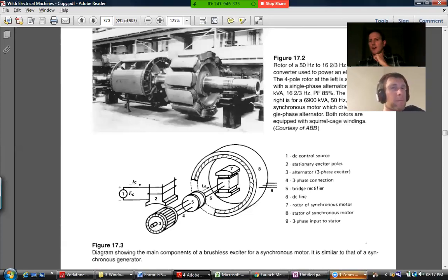It's coming via this thing making this thing into a motor. The motor's turning, and this is like a mini generator turning because the motor's turning, which is generating back into it. So you've got a kind of a motor and generator happening at the same time. But the one's extracting a little bit of power out of the grid, requiring some torque to turn it, and the other one's extracting a whole lot of power. That's the majority of the torque, which would then be going onto the load.